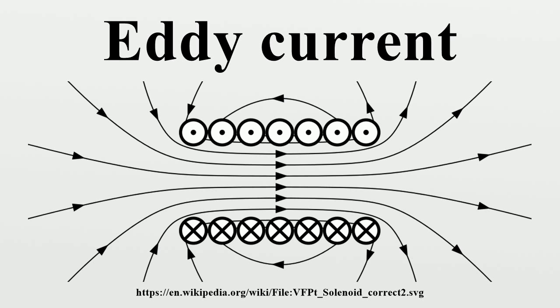Self-induced eddy currents are responsible for the skin effect in conductors. The latter can be used for non-destructive testing of materials for geometry features, like microcracks. A similar effect is the proximity effect, which is caused by externally induced eddy currents. An object or part of an object experiences steady field intensity and direction where there is still relative motion of the field and the object, or unsteady fields where the currents cannot circulate due to the geometry of the conductor.